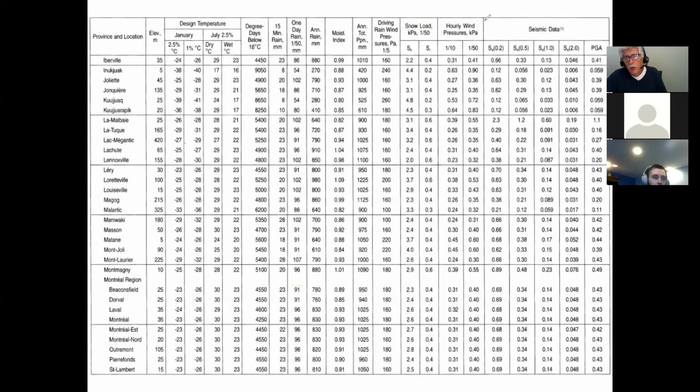And then next week, we will be talking about this. This is the wind pressures. Now here they have 1 in 10. In other words, this used to be used before. We do not use this anymore. This means that this wind pressure is going to occur, or has occurred, once every 10 years, or when they monitored all the readings over a 10-year period, this was the maximum value that they found. And then the same thing here. This was 1 in 50, the same that you have here.